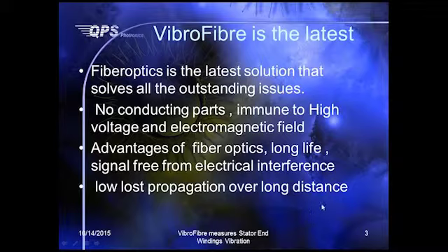Actually, fiber optic is the latest solution that seems to have solved all the outstanding issues historically. In early days, this stator end winding problem was solved using piezoelectric sensors. And piezoelectric sensors have conducting parts, and that raised the concern about causing partial discharge. And so it requires shielding. And this has been a problem that we still have to deal with.